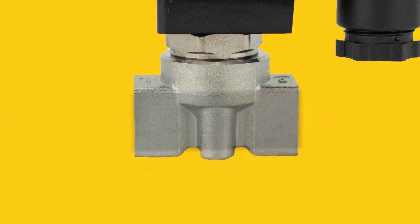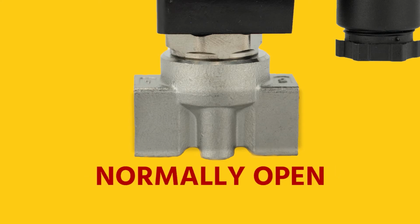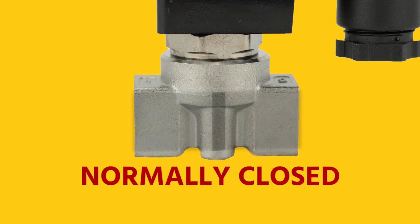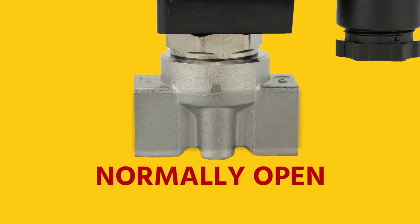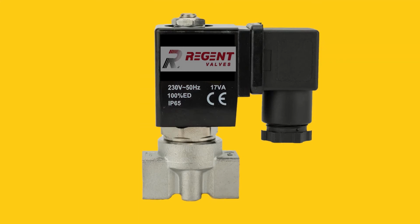Two-way valves are therefore often called shut-off valves. They can be normally open or normally closed. Normally closed means that the valve opens when energized. Normally open means the valve is open in rest position and closes when energized. They are often used in pneumatic applications where the supply of air periodically needs to be closed off.